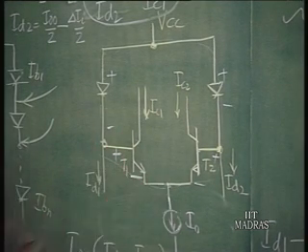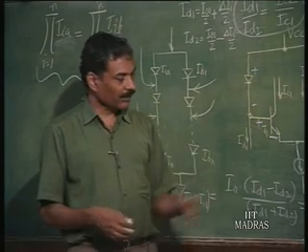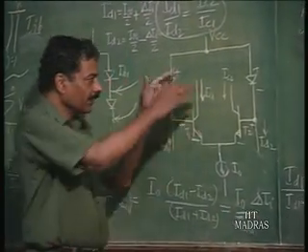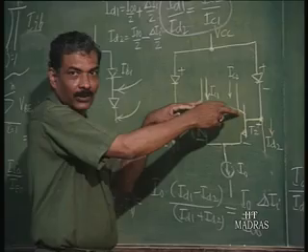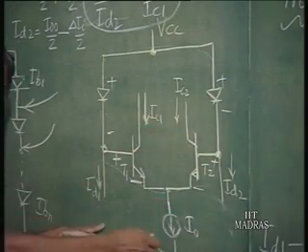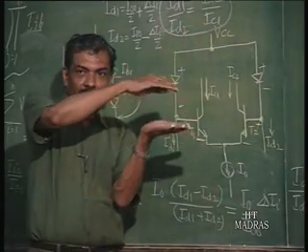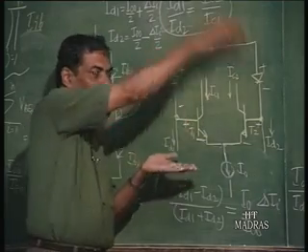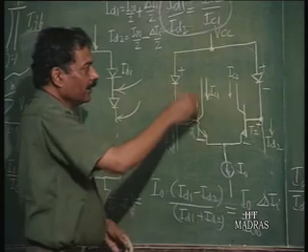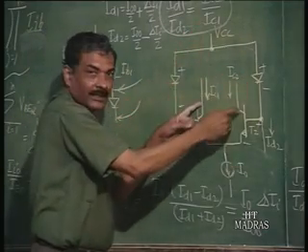So, these circuits are nowadays being used as wide band amplifiers with constant gain, and you can reach the required gain by simply cascading such structures, because this differential input could be the input to the next stage, which looks exactly identical. Only thing is the operating current of that is, let us say, 10 times more than this. So, you can put one structure over the other structure, that is why it is called a cell. The next stage will have two other diodes connected to the same VCC with this as input now.